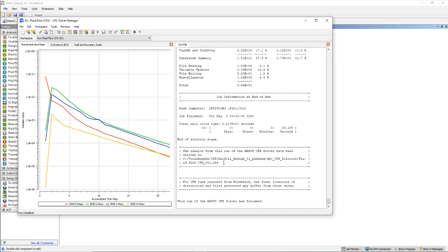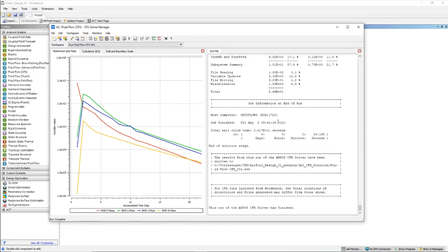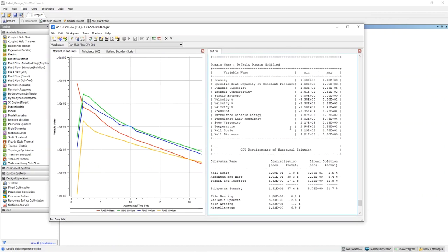If there are not big differences in the mass balance, if the mean residual over all the cells is lower than 1e-5, we can say our balance is closed and our momentum balance is fulfilled. That's important. Please have a look, maybe read a bit here.